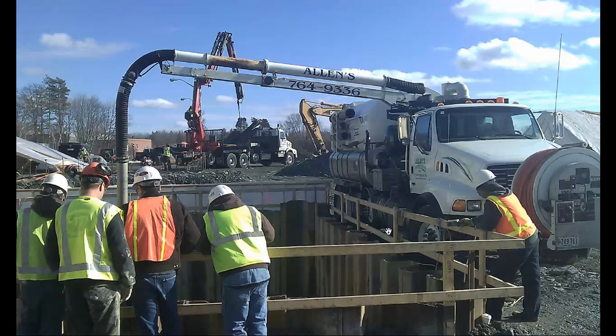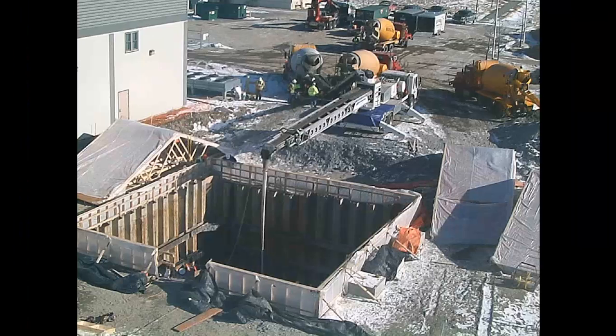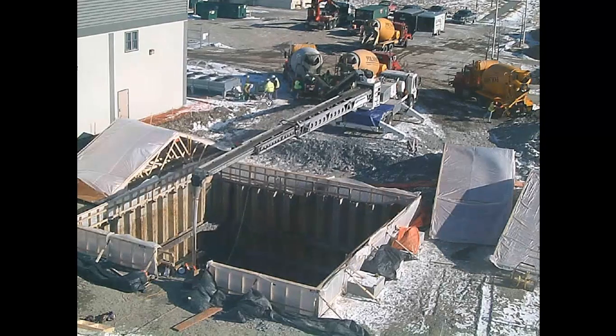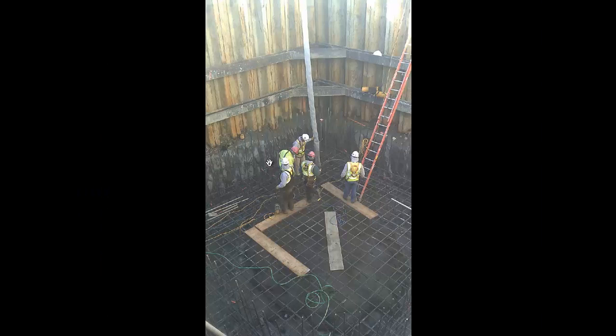Now, what we've got now is the giant vacuum, and the guy standing around watching it. Now we're starting to pour the first lift of concrete in. So we've got our concrete trucks showing up one after another. They're pouring this at about, I think, 4 feet at a time. This conveyor just brings the concrete out, drops into a chute, goes down, and they have a guy down there just directing it, and there's a guy up here with a radio control that can move the conveyor one way or the other. You can see he's moving it back and forth. I'm not sure where he is, probably standing over here with his little radio controls.